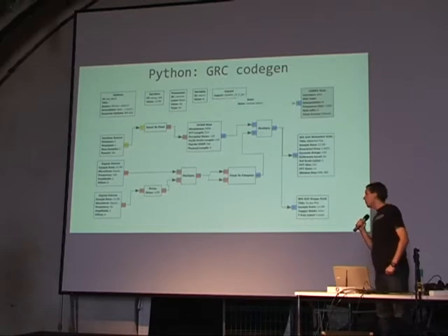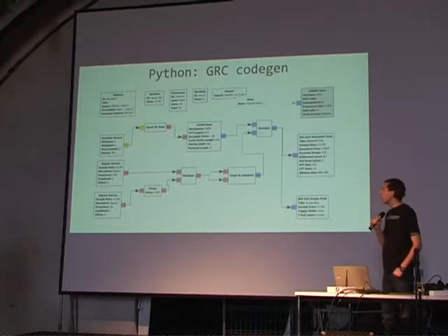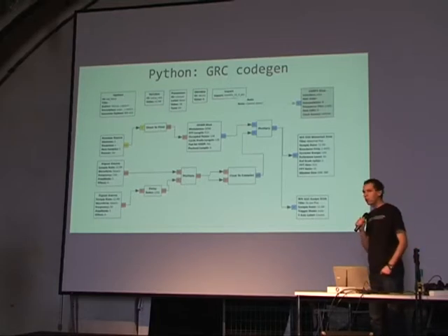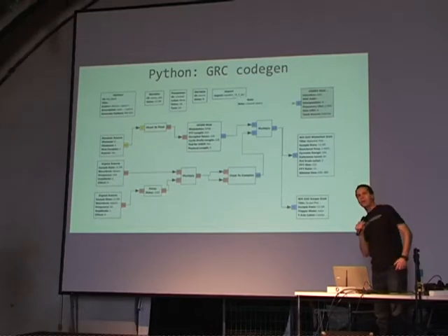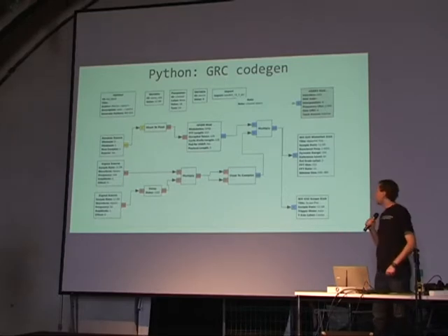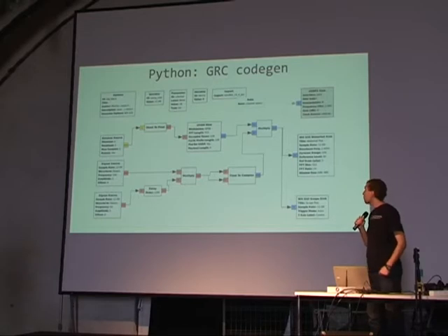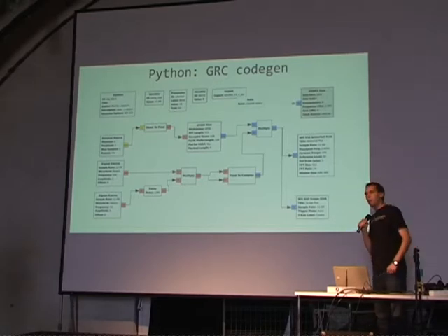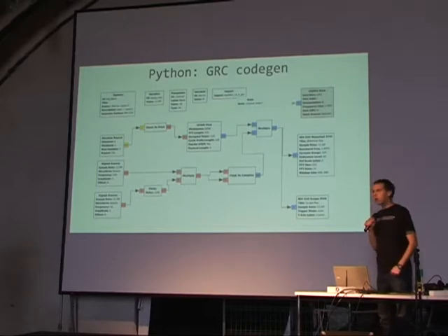And since I mentioned that the GRC defines a code generation, it is putting this together as a Python script that is controlling the appropriate C++ classes that realize the signal processing. What I have done here is I have used a set of parameters. Well, parameters are named so that you can pass them with command line arguments and start your script and control it.